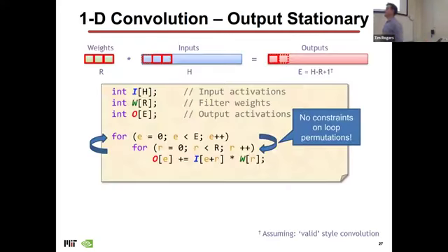Now, we're going to see this as a theme when we go through the rest of the different types of ways we can construct DNN accelerators: we can take the core convolution and turn it into this simple loop example. And they do this in the tutorial. So let's go away from 2D convolution, because 2D convolution makes things trickier. Now everything has an X and a Y dimension, so you end up with extra loops to go over both X and Y. Let's just think about 1D convolutions.